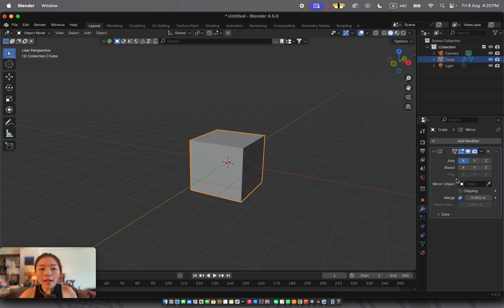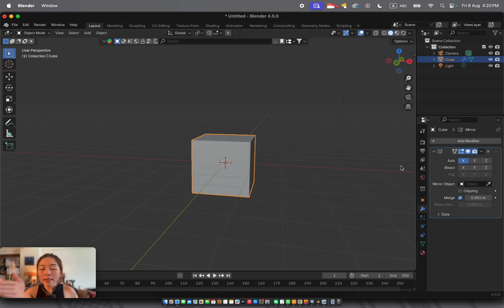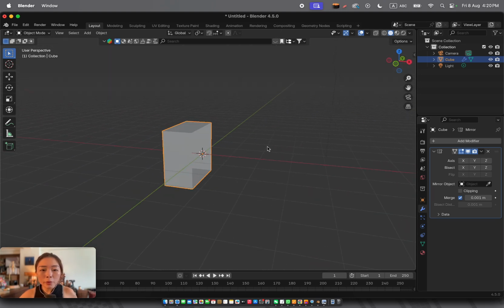The mirror modifier by default uses the x-axis as the mirror line. Because I deleted the right side of the cube, and by default when we introduce the mirror modifier, of course we are going to clone it from the left-hand side to the right-hand side. If I am not using the x mirror, then it will remain as half.